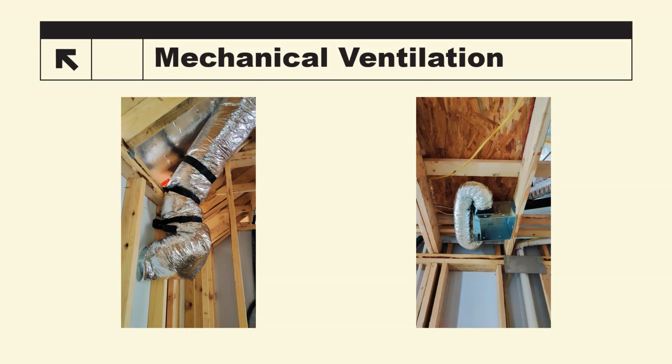This would need to be fixed for Energy Star, and now in 2021, when you're doing mechanical ventilation verification of fan efficacy, it'll have to be tested and found out that if it doesn't pass, that means it's going to have to be done again. So there again, there's no way to fix it without cutting sheetrock, but you have to have it hit 50 CFM to pass, and you're probably not going to get there.